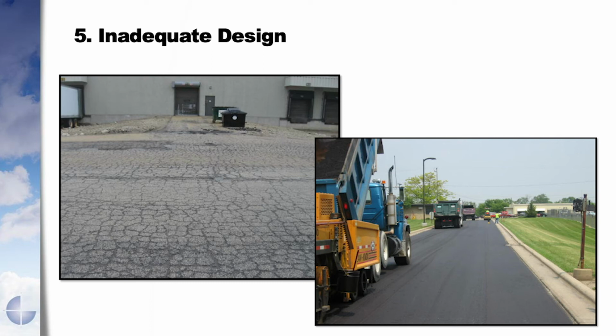It was like the concrete example I showed on the previous slide. The asphalt wasn't thick enough, so the heavy loads were breaking the asphalt against that hard stone base. So what we did was, after we removed the asphalt, we removed some more of that stone base down so that we could replace the asphalt with a thicker asphalt, and it's performing very well.